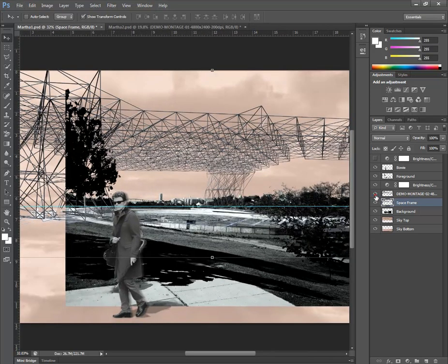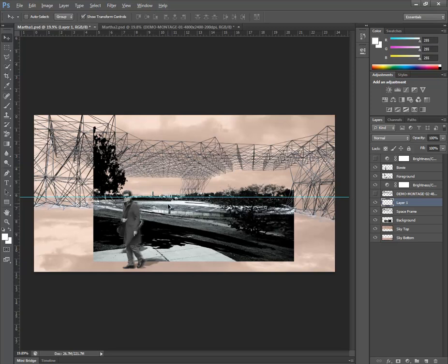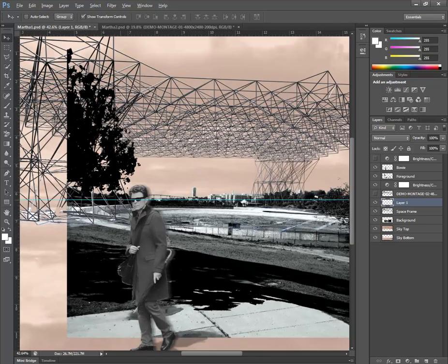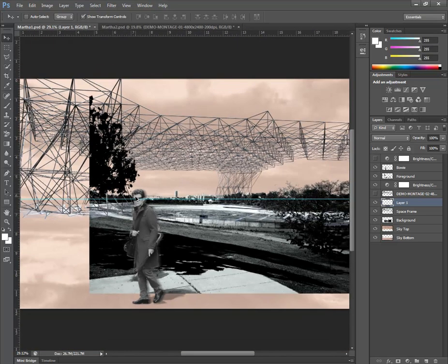Do you need a new layer for the guide? You don't have to. You can create another layer that has just guides on it if you want to, or if they're going to be so temporary that you just use them for that immediate purpose, then you can just delete them, or you can turn guides off if you want to.